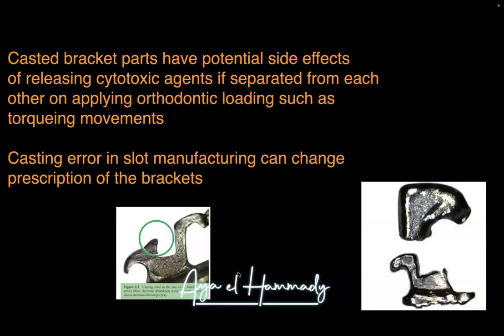As we mentioned, in the casting here, it's like a puzzle. I'm going to collect all the parts and try to put them together. During the puzzle process, I may have a torque problem. I may not fix the parts together in the inclined slots to give me the proper tipping, or I didn't put the mesh in the proper place.